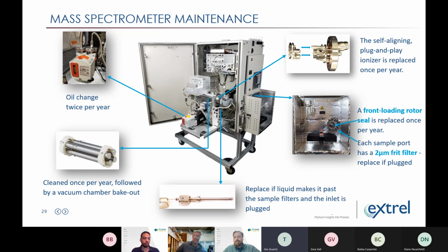We've got all the common tools, but in some cases for GCs, you need a special tool to hold the furnace tube so it doesn't break, or you need a tubing fitting feeler gauge so you don't over tighten the tubing. There's a host of little special expensive tools that are required. So I'm just trying to cover our bases on this.